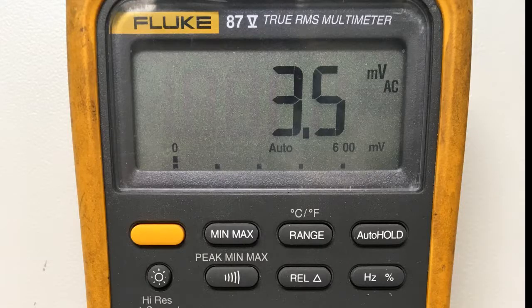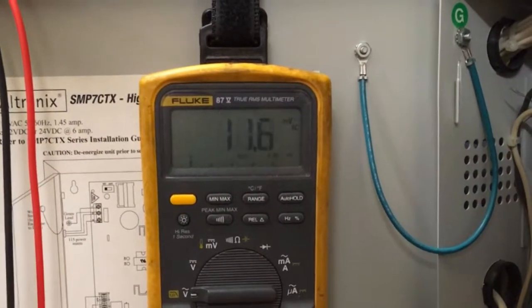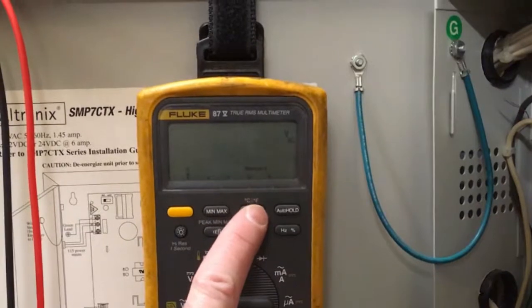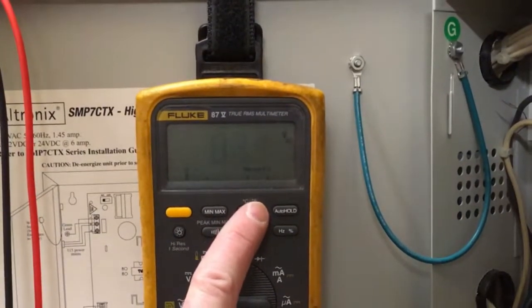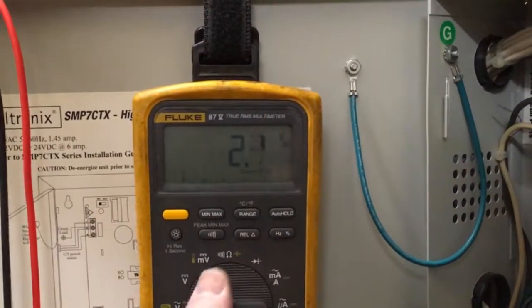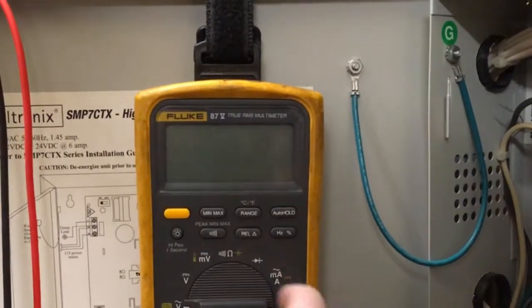Most meters will default to an auto range mode, in which the resolution is automatically selected based on the measurement value. The mode is indicated below the measured value. Pressing the range button will manually adjust the measurement range of the meter. If you do this and wish to return to auto range, you must turn the meter off and return it to the AC volts measurement.